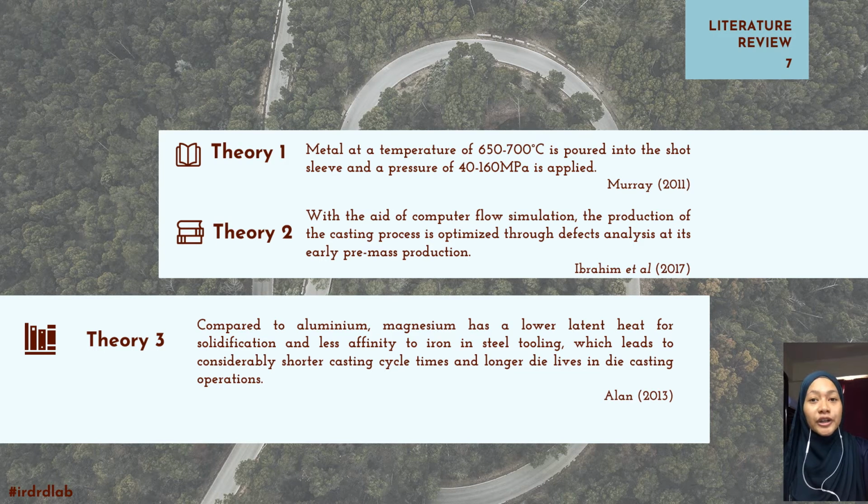Based on the first theory, which is from Murray, it is important to have a certain set of variables, which are temperature and pressure, to complete the die casting procedure. While in the second theory, Ibrahim says that computer flow simulation is really important and helpful to optimize the procedure as well, going through the defect analysis before any die casting processes. While theory 3 stated that magnesium has a lower latent heat for solidification and leads to shorter casting cycle times compared to aluminium.